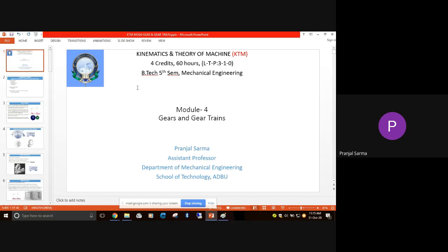There we saw that if omega 1 by omega 2 is considered, with suffixes for driver and driven, it is inversely proportional to the radius of the wheels. Being inversely proportional to the radius is similar to being inversely proportional to the diameter, and the radius or diameter of the gear blank or gear wheel gives you the indication about the size.